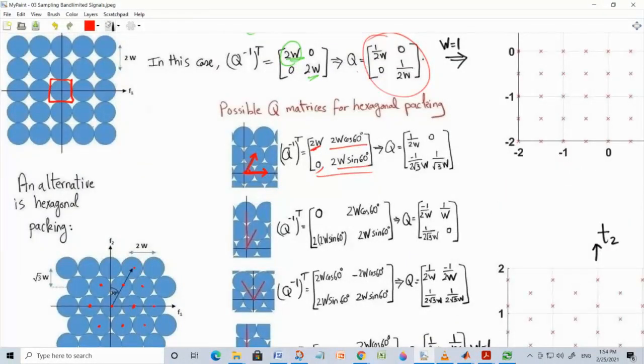It is a story. Again, if you have a band-limited signal, as in 1 dimension, there is hope that you can reconstruct your signal. This is a result for all signals, 1 dimension or more. But you need to avoid aliasing. That's the essence of the sampling theorem that you have studied in a previous course: signals and systems, digital signal processing, digital communications, whatever. So the idea is that you can reconstruct your signal so long as you sample it in such a way that you avoid aliasing.